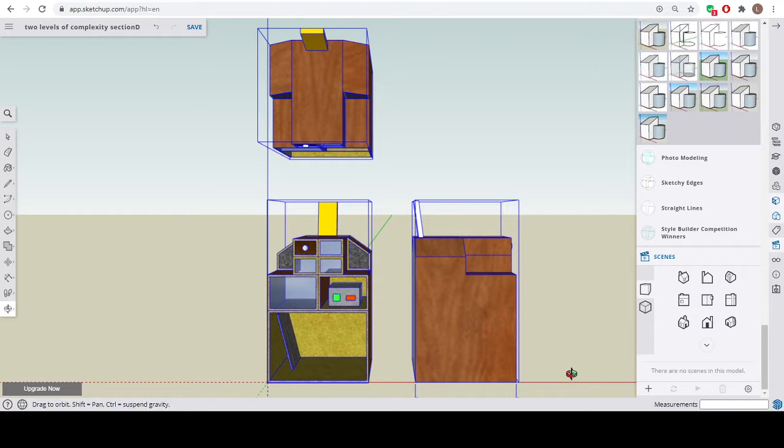If you're not doing it like this, if you're not doing front view, side view to the right and plan view above, looking downwards, then that is not considered third angle orthographic. There are certainly orthographic views, but this is the third angle orthographic convention. So I just wanted to get that out of the way.